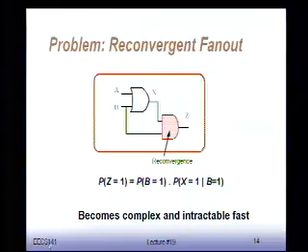Okay, so let's come back to this problem: analyzing power. We could do this very simple trick, move from the inputs to the outputs, and get the whole thing analyzed, and we're all done. But as I said, it doesn't work very well for sequential circuits, and it doesn't work very well for this kind of case where you have, for instance, a reconvergent fan-out, as you can see.